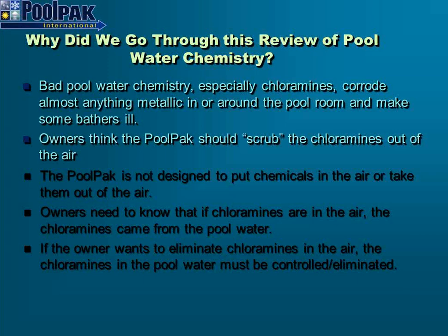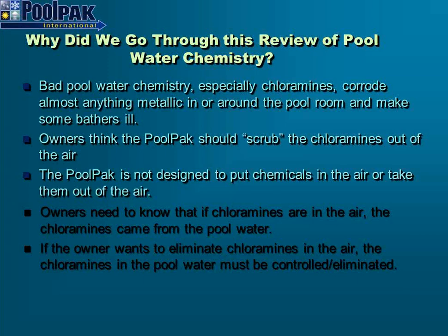Sometimes owners are under the misimpression that PoolPak should scrub chloramines out of the air. That is not what a PoolPak unit does. It just dehumidifies, cools, heats, and ventilates the air in the natatorium. We don't remove or put chemicals in the air, and owners need to know.